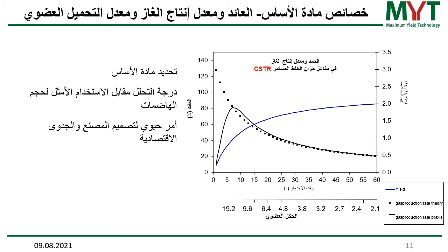Again, since the degradation rate is substrate specific, of course also the dimensioning of the plant and the yield you can obtain after a certain retention time is substrate specific. And a long retention time results, of course, in very large digesters.